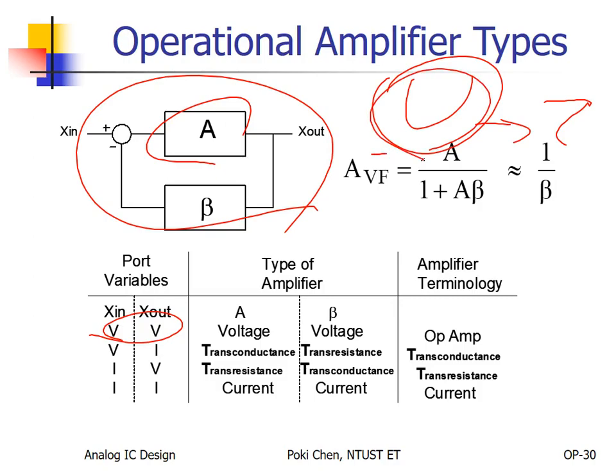So that is a voltage oriented learning process. Students, engineers focus very much on voltage instead of current or the others. But I need to warn you again, for CMOS analog IC design, we focus on current very much. Usually, current is the input, then we generate maybe voltage for output or something.